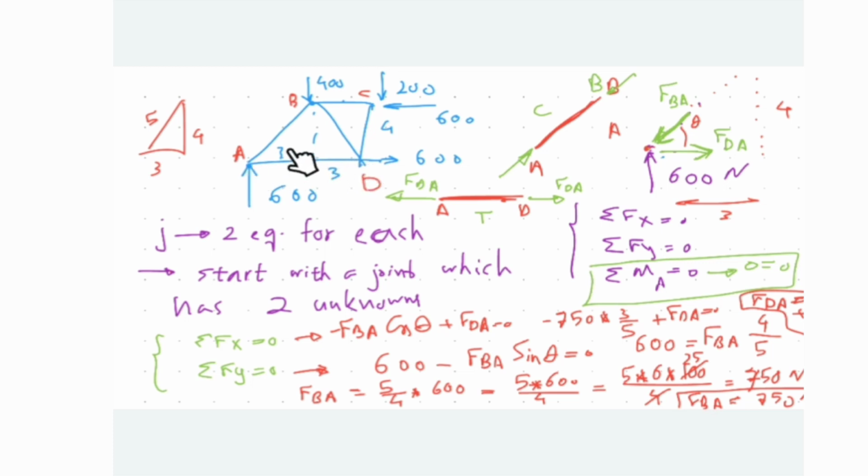The question here is how to put the force. We know the magnitude of that. This is FAB, which is applied on this point, but how is the direction of that? We need to do the same reasoning over here, because here we said that this is the force which is applied by this guy, and then we put the reverse of that on this point. For keeping the static equilibrium conditions for AB, we need to put this guy here.